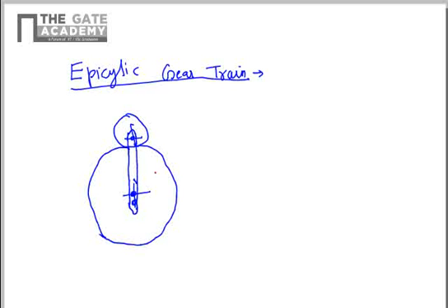In this case, the bigger gear shown here will be fixed and the arm will be given some rotation. Since this is rotating and these two are in mesh, this is the smaller gear. So the smaller gear will start to rotate as well as move in the translational direction due to the movement of the arm.